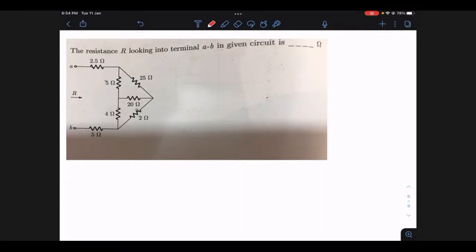So in this case, I'm going by this star delta transformation. I have two options actually. One of the options is you can think of this as a star network. You can have its equivalent delta, which one I'm highlighting. Otherwise, you can think this is a delta, you can have its star. So three options are there. Whichever is comfortable to you, you can go through it. So what I'm doing is, let me convert this delta into star. So this delta I'm converting into star. So this value, let's call this RA.